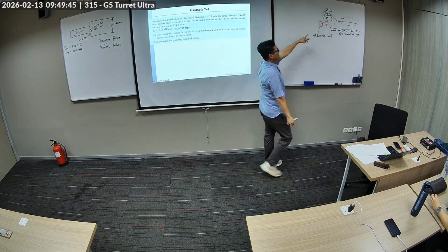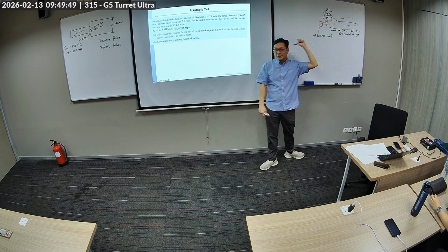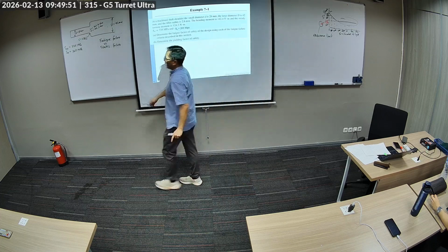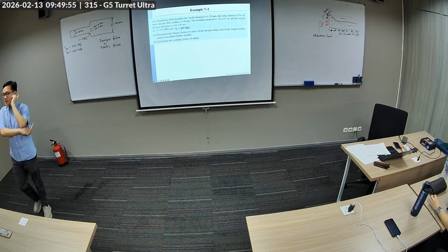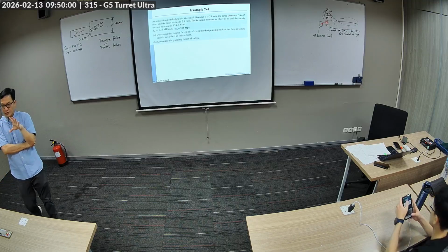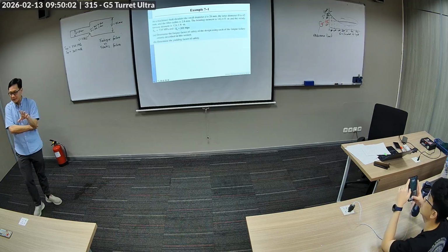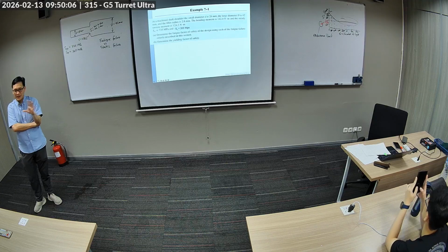So this is a very important number, don't you think? So 205 MPa is the magic number. If I make sure that my shaft is stressed below 205, then my shaft will have infinite life. No fatigue failure.